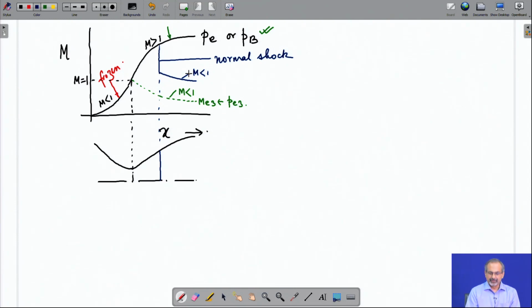So, going by the geometric feature, that is how it is going to happen. What if you are having a slightly different pressure in the exit end, but it is still not as strong that it can create a normal shock within the nozzle. So, there are other possibilities which can occur. So, let us try to figure out what those possibilities are. So, let us additionally make a pressure plot. We tried to understand through the Mach number plot how things are working. Now, let us try to work out how in terms of pressure the things are happening.